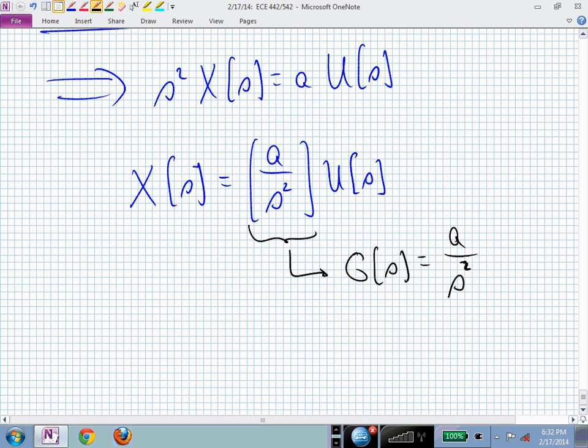I've got two, don't I? That's where zeros equal poles, always, if you count infinite zeros and finite zeros as a quantity of zeros. So the number of zeros always equals the number of poles, if you allow for infinite poles and zeros. Typically, we only talk about finite poles and finite zeros, but in these discrete equivalents, we are going to need the understanding of an infinite zero, because we will map those to certain places.